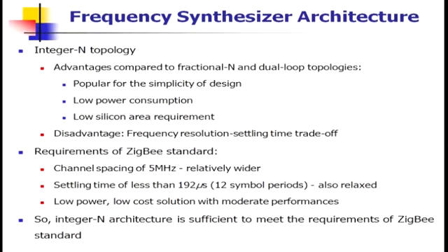But look at here, if you design the frequency synthesizer for your TV tuner, the frequency is 426 to 600-something, 70, and there are more than 200 channels. The channel spacing is not limited to the integer mode, so you have to actually divide by a fraction. That means if you have gigahertz, integer mode gives you a megahertz kind of spacing. Clear? Now you need kilohertz, therefore you go for the fraction. That means your divider will now be N plus 1 by n.